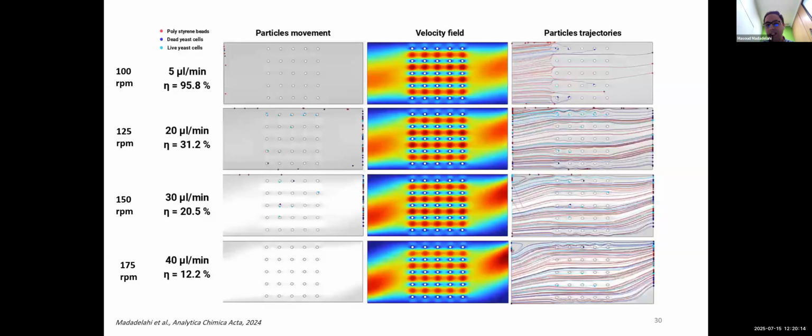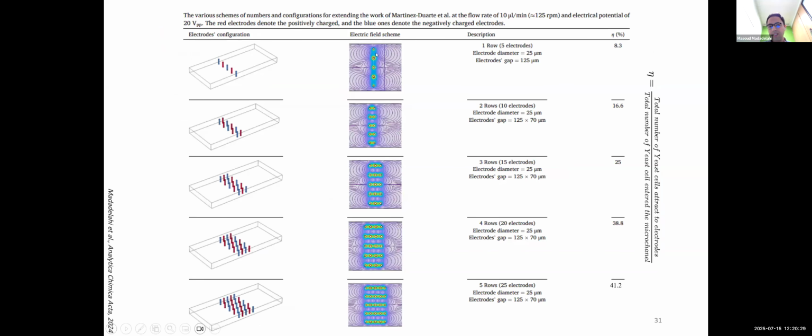So we do have the electric field in our simulations, right? Because we are applying that voltage over the surface of these electrodes, and then we will have an electric field. This is the electric field distribution that we have in our system, and that electric field creates the DEP force, right? And that DEP force goes to particle tracing, or Newton's second law equation, to affect the particle trajectory. Okay. Thank you.